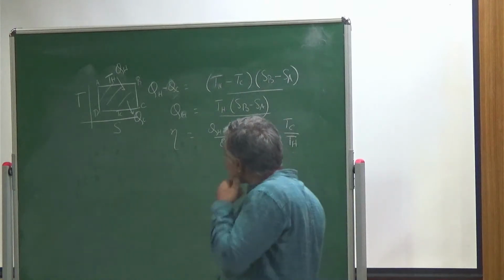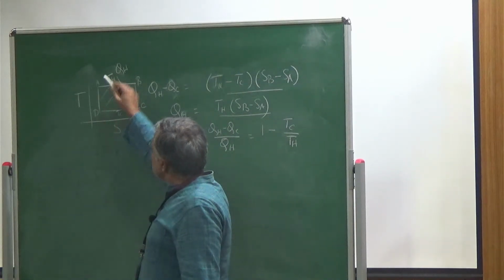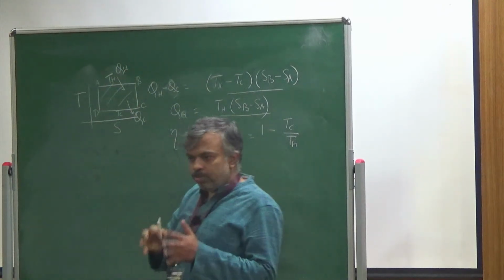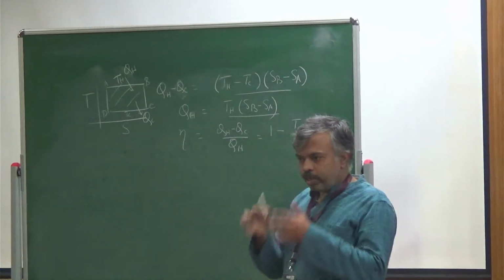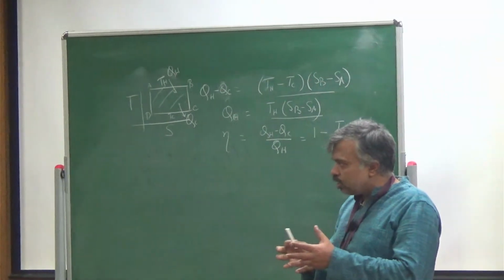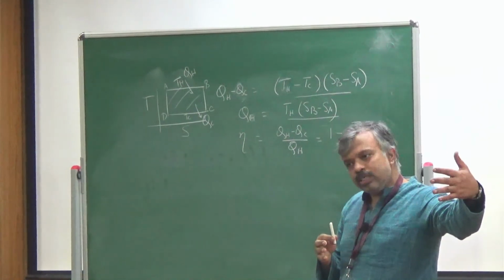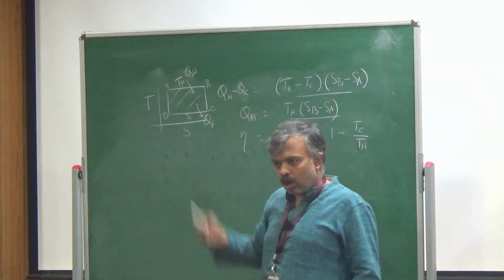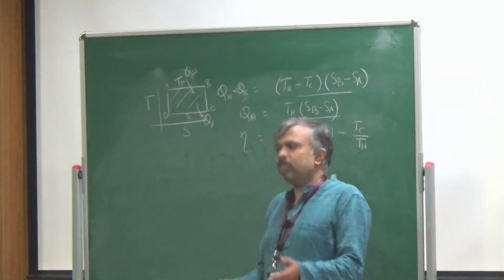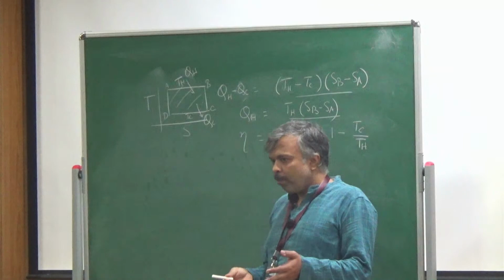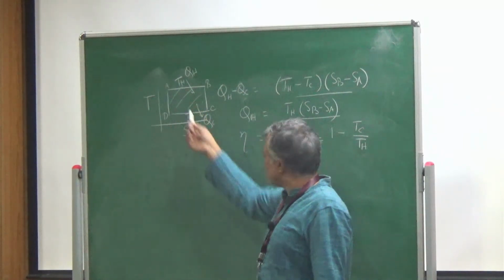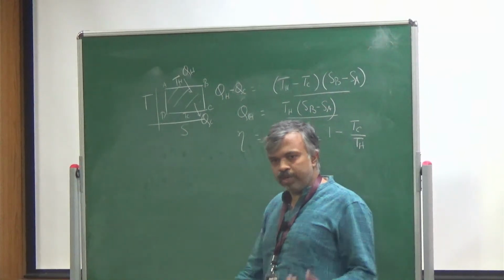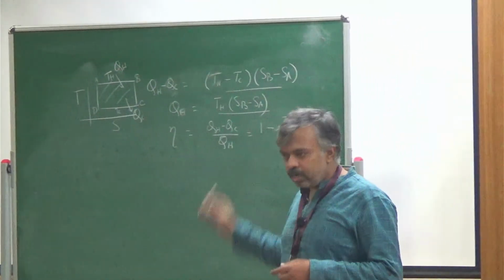Now, the point is, see, if along this line the system is in equilibrium, that means the temperature of the working fluid inside and the temperature of the bath is the same. Then the first question is how we get this QH at all. Why is this QH flowing, because there is no temperature gradient. Correct? So if there is no QH, no work. So efficiency is 0, no input, no output. Right? So that means that it is a very, very idealized condition.